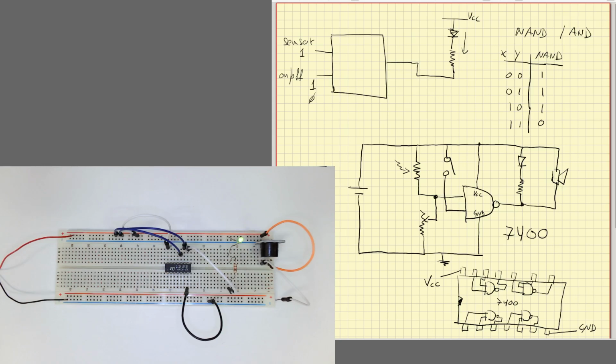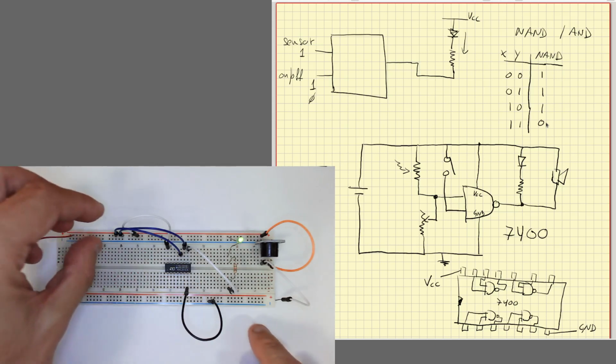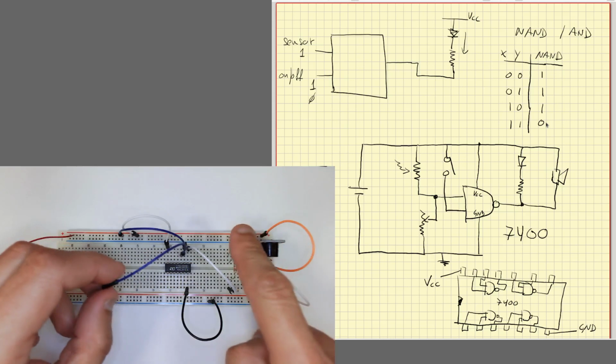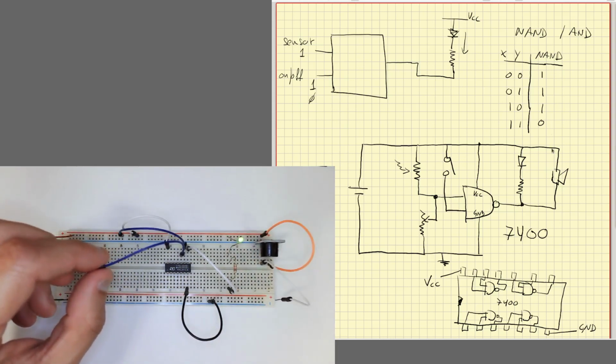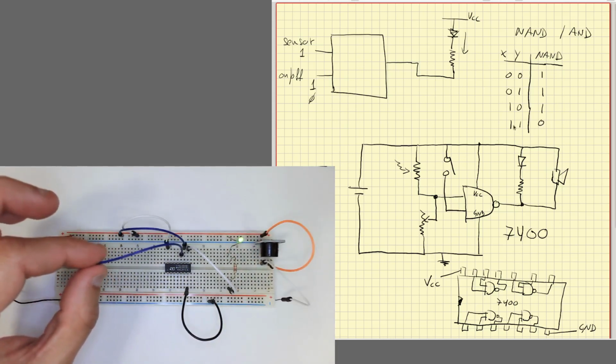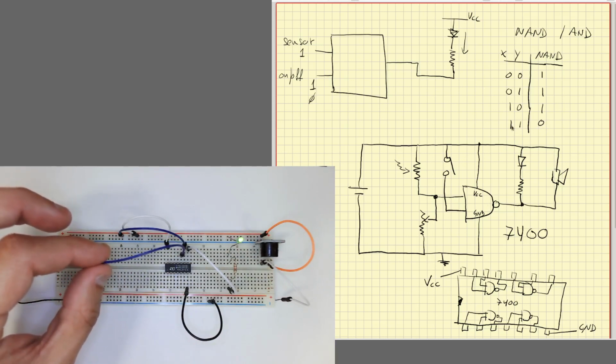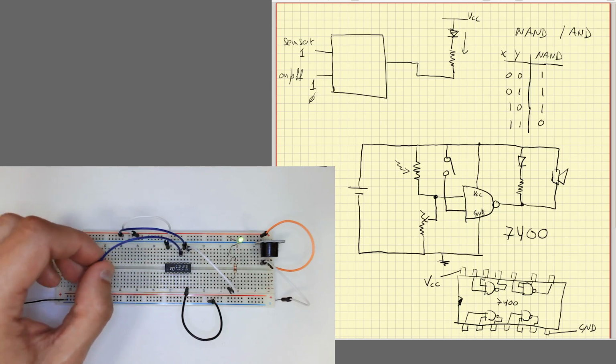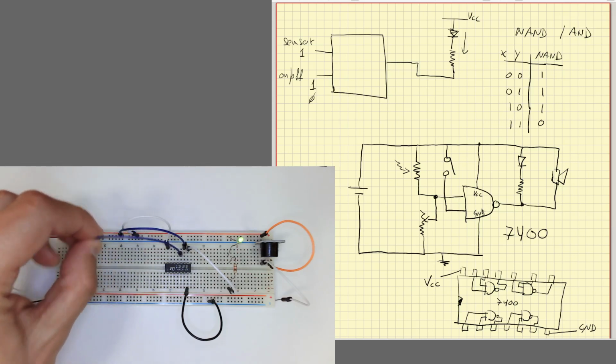In this case I have my circuit working properly. As you can see, if I do not connect some of the inputs, the LED is on, so the output is also 0. So not connecting an input makes the NAND gate behave as if the input is 1, but it's not recommended, because the inputs of a logic gate should always be connected to some power rail.